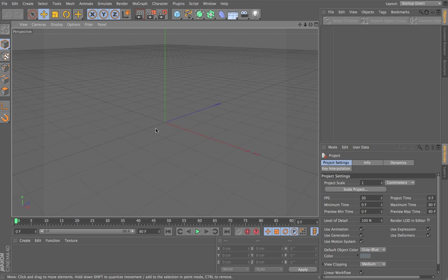Now, the main question I was asked by my fellow C4D user, Mustard Seed, was that Booleans create bad topology. That is the case if you don't prepare your topology to accommodate the specific Boolean. I'll give you a very small example before I begin.